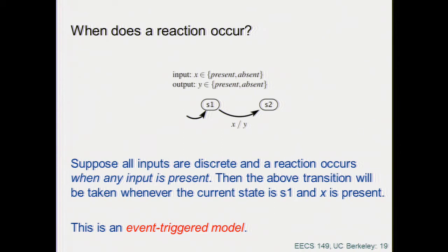But when one of you tells me that a synchronous system is one where there is a clock, you are fired. For sure. That has nothing to do with it, because this model, the finite state machine model, is without time. There is no notion of time in it. What matters in a finite state machine is the transition.